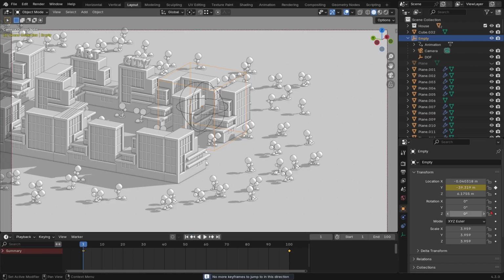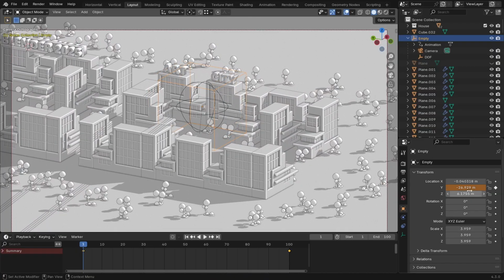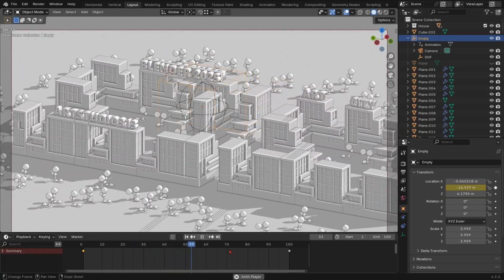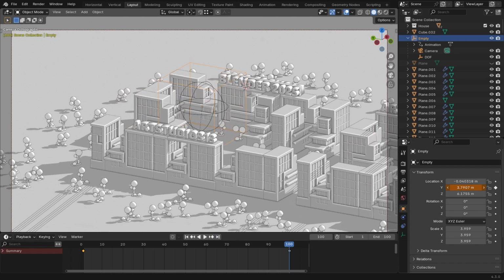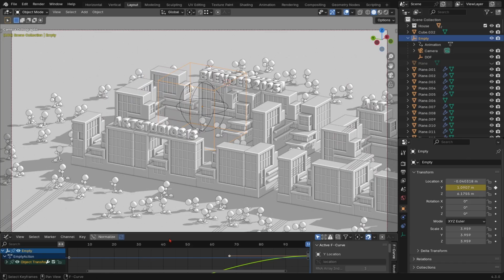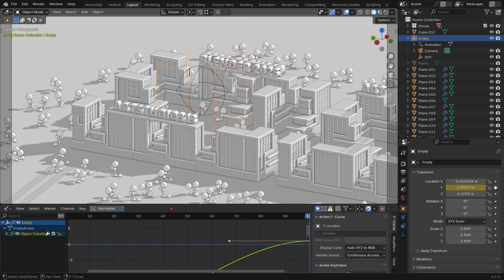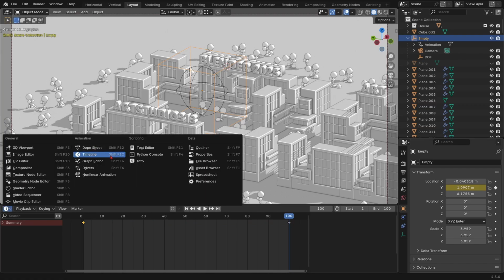So let's move it back so that we can start from here. Replace it. So let's press numpad slash, and you will see if I just right click, it's in Bezier. You can press T to open up the set keyframe interpolation mode. We can, for example, press T again and set it to Bezier instead. And now let's see how it will work.